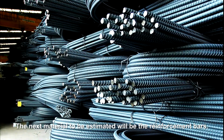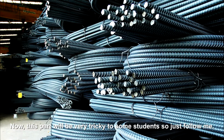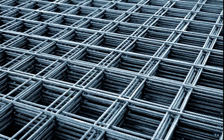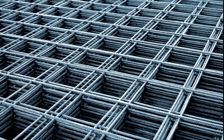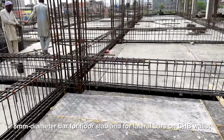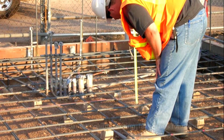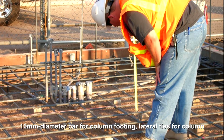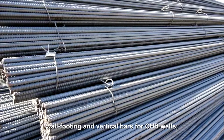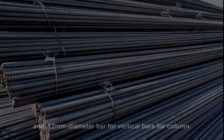The next material to be estimated will be the reinforcement bars. Now, this part will be very tricky to some students, so just follow me. We will use 3 types of deformed bars: 8 mm diameter bar for floor slab and for lateral bars on CHB walls, 10 mm diameter bar for column footing, lateral ties for column, wall footing, and vertical bars for CHB walls, and 12 mm diameter bar for vertical bars for column.